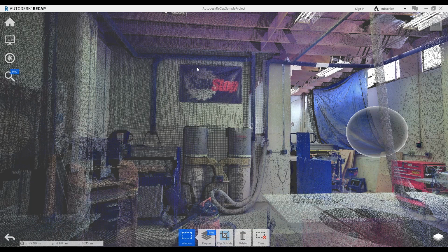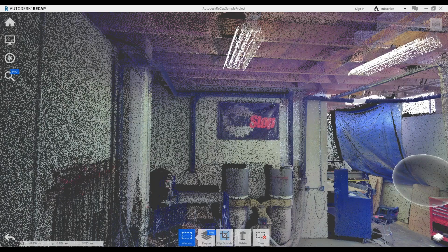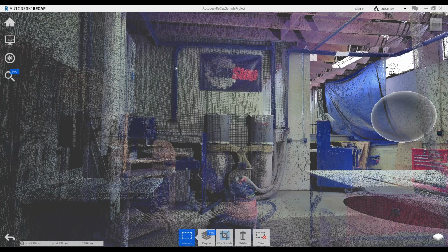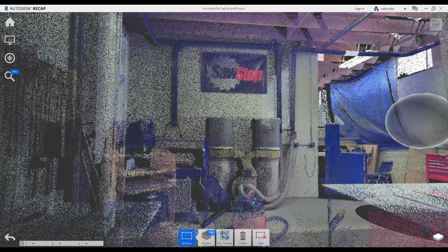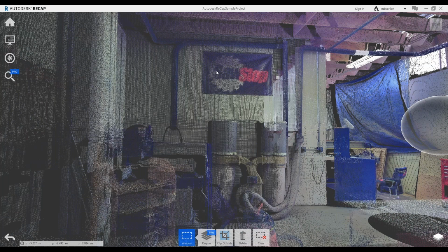Once you've done your Revit modeling in here, you can toggle that off, switch that on. So there is a systematic way of using Recap. And the big misconception is that if you do the scan, you've got the model. Unfortunately, we're not there yet. There are some technologies, like ClearEdge and stuff, that actually do that. But at the moment, once a scan is processed, you import that, and then from here, it's basically you tracing, if I can put it simply, your model. So yeah, that's just a quick rundown on Autodesk Recap. I'll check back in with you later.